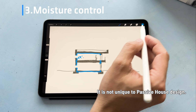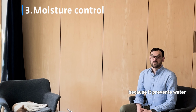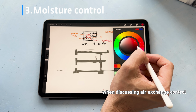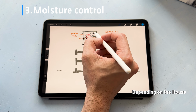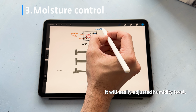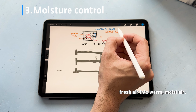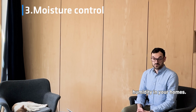It is not unique to passive house design. Nonetheless, it is crucial because it prevents water from infiltrating the construction. The ERVs I mentioned when discussing air exchange control are also important for moisture control. Depending on the house climate zone, ERVs can be equipped with a dehumidifier. It will easily adjust the humidity level. For example, in the winter, it will turn cold, dry, fresh air into warm, moist air. The opposite happens in summer when you need less humidity in your homes.